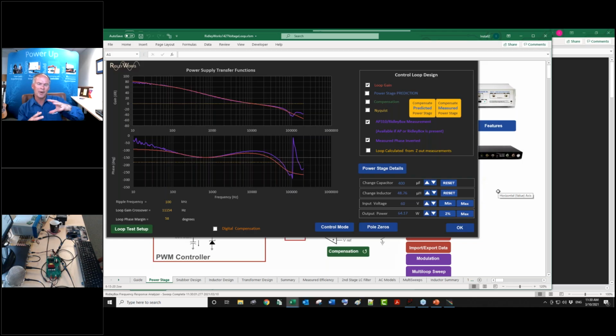The only way to debug that system when you see it oscillating at different points is to set that PFC circuit to DC with a DC input and measure the loop. So yes, sometimes, but the whole class of inverters tend to be much slower loops and much more predictable. They tend to be digitally controlled, and they're not doing so many of these loop measurements. But again, every system is a little bit different.